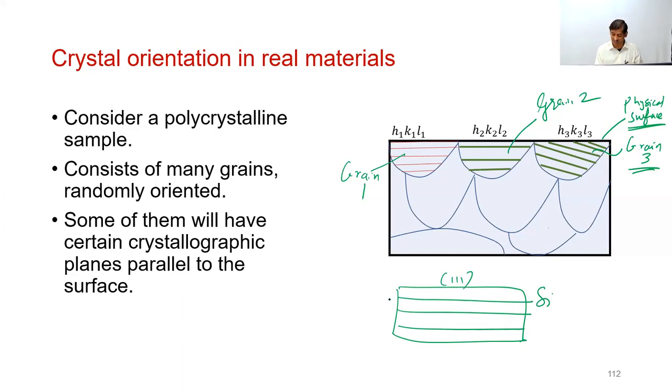This would be your d spacing between those planes. The sample itself may be of the order of millimeters or centimeters, so this would be a thick sample. There are certain uses for these single crystal planes. You also need them for turbines. If you want to maximize high temperature performance in a material, then there are certain planes which are desirable.